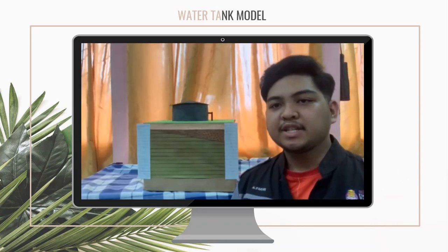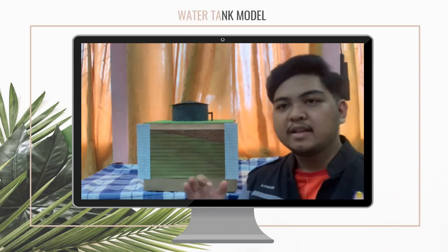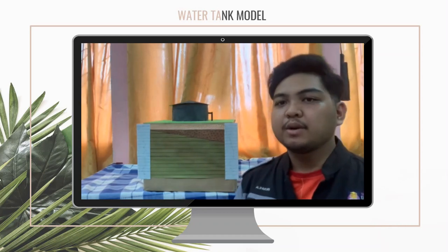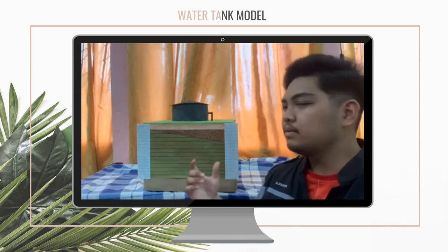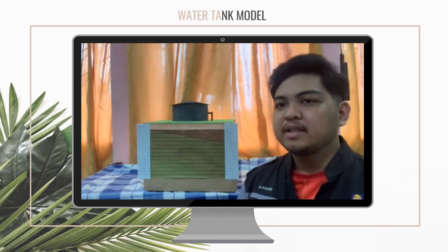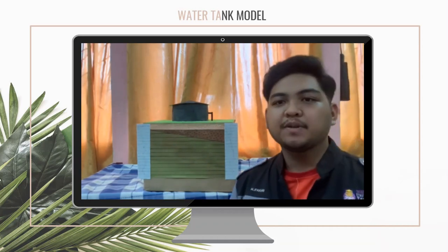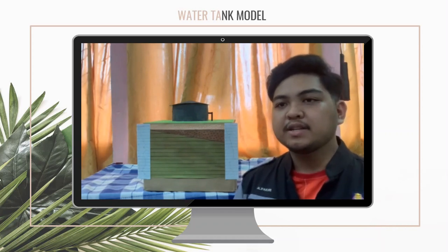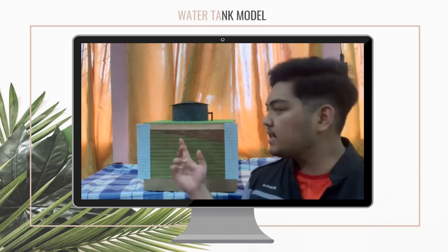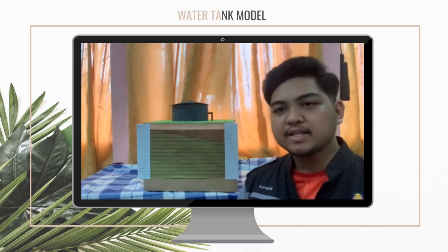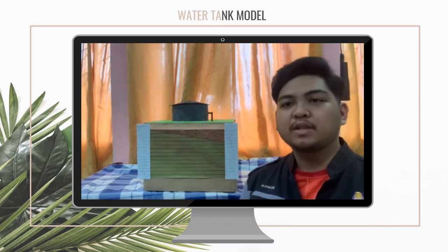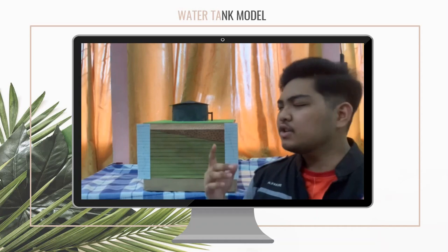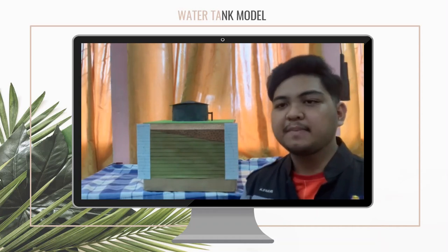Based on an investigation of the subsurface profile and vertical stress distribution on boreholes 1 and 2, we can conclude that borehole 1 is the best proposed location for a water tank. The soil in the borehole 1 location is ideal since it has a sandy layer on top, and the soil is clayey from 0.3 to 10 meters deep. Because borehole 1 has a higher bearing capacity, it is more suited than borehole 2.